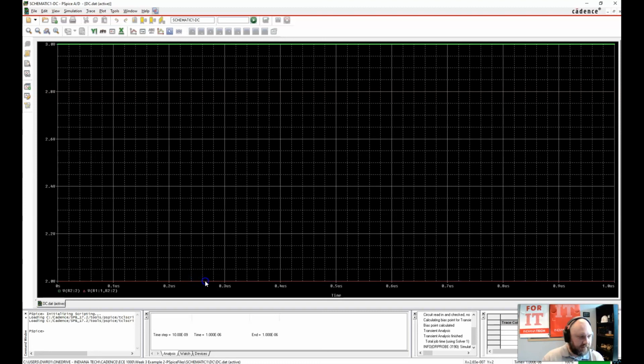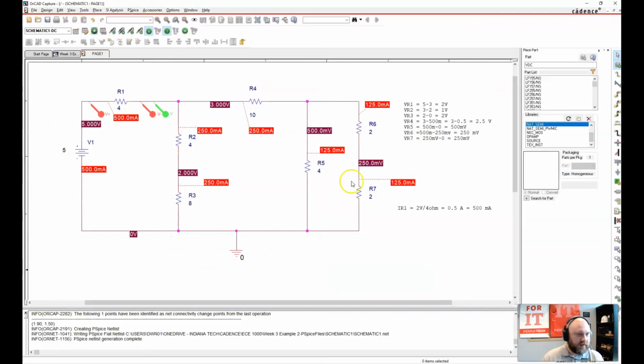And it's not letting me really select this very well. But it's the one on the very bottom here, and it's 2 volts. Well, wait a minute, 2 volts is the voltage across it. So that differential probe will let you measure the voltage across a component. The positive side is always where you put the first one, and the negative side is where you put the other one.